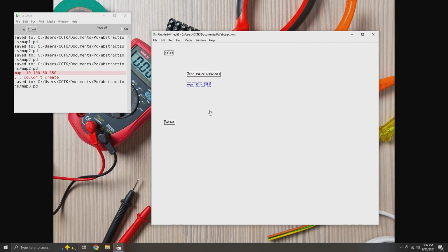That is how you tell expression boxes to use the first inlet, and you're also telling it that it's going to be a float value. You could do $I1 if you know it's going to be an integer. In this case, we might end up with a ratio of fractions, decimals. Might not be a pretty number, so you want to make sure that you have that be a float to handle when it's not a perfect integer number. And then that's going to be multiplied by $1.